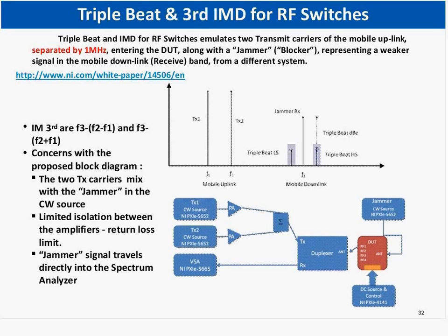And now what I would like to do is use a National Instruments published white paper that is available on this website. And I would like to take their setup and put in the flavors of everything that we learned thus far. In this measurement, we have 2 TX signals in the download band, mobile uplink, and we have a receive filter. We have a receive jammer right into the receive band. Again, 3 signals, TX1 and TX2. So we are looking at the National Instruments test setup.